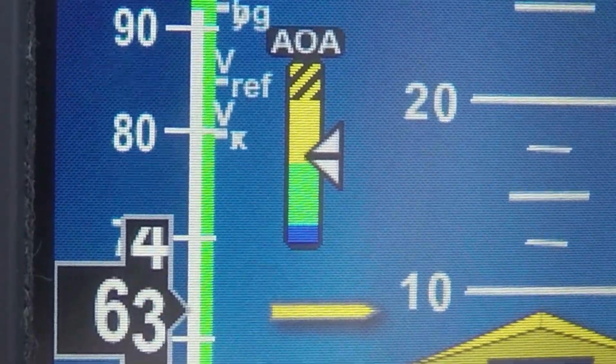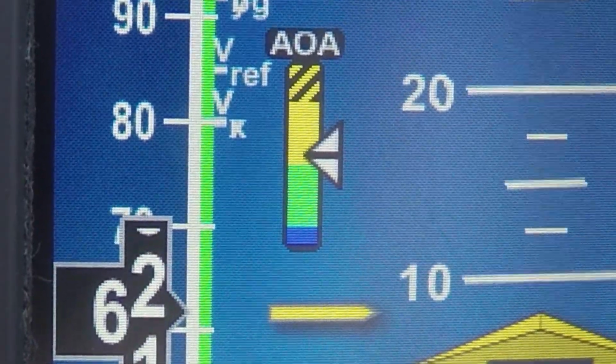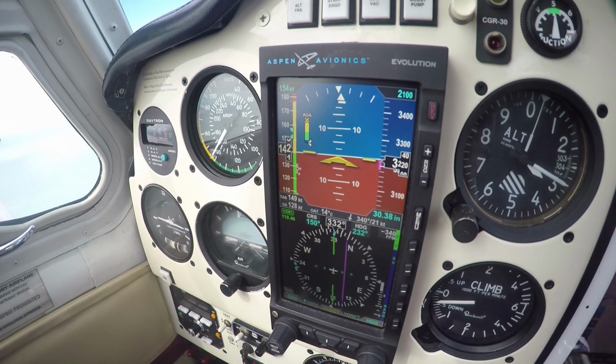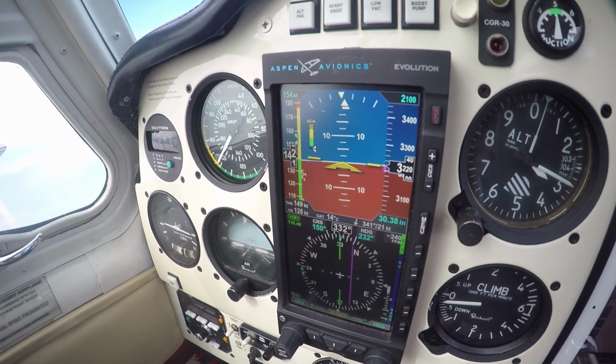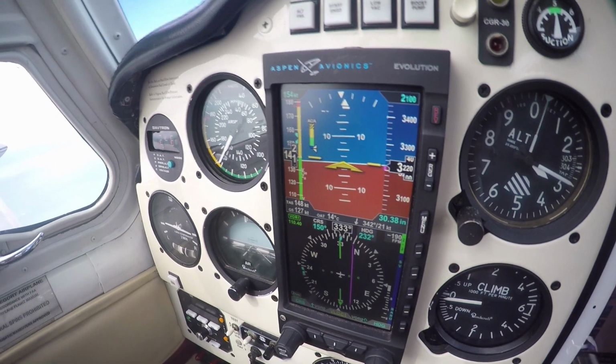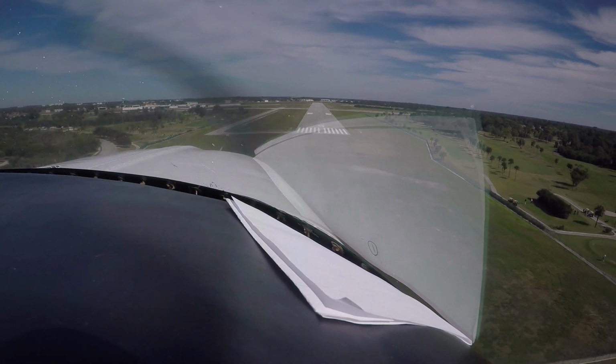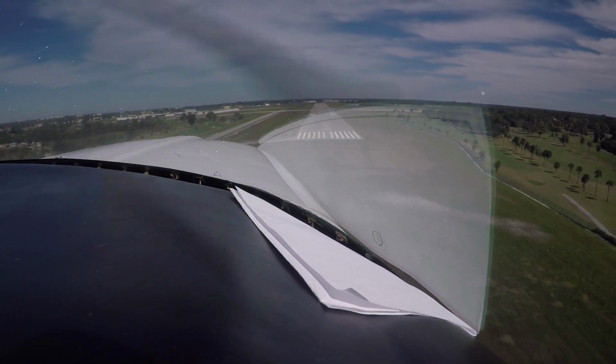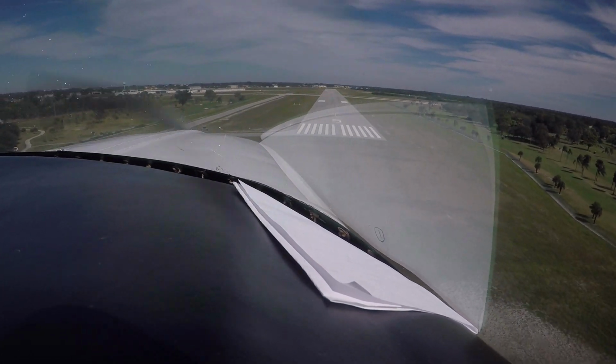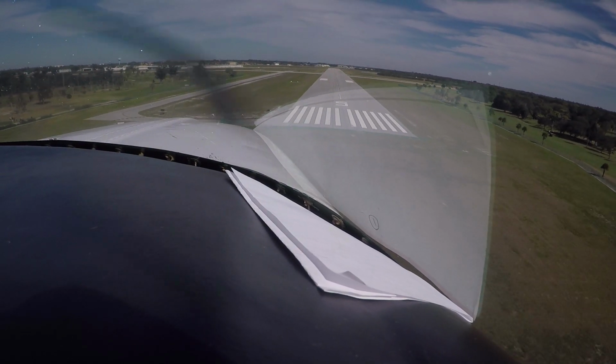You can see that the airspeed indicator actually indicates a speed lower than the published recommendation. At altitude, you can experiment on how far into the yellow you can go before either getting on the backside of the power curve or reducing the stall margin beyond your comfort level.